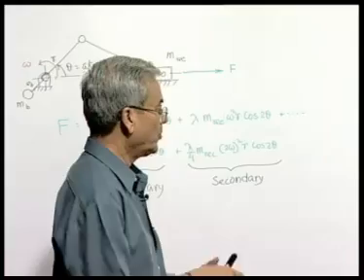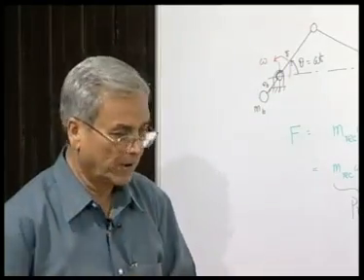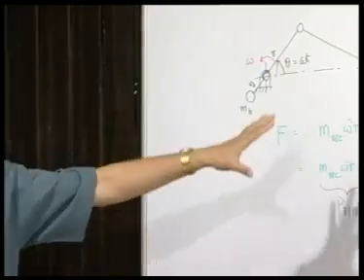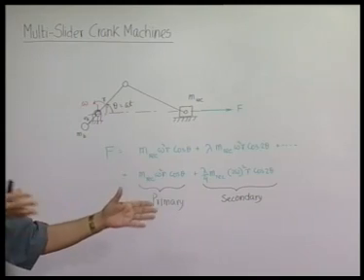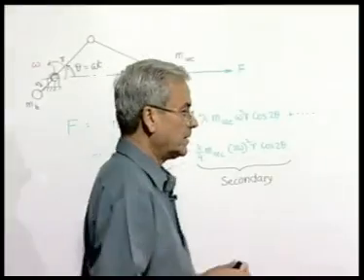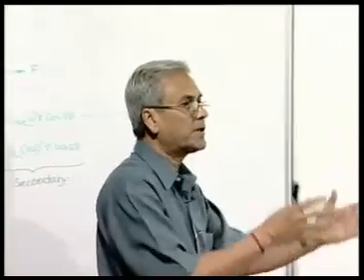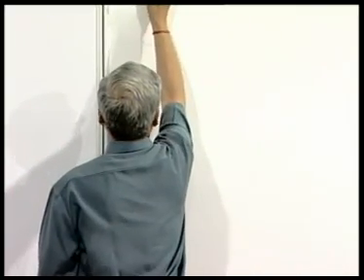And now, what we start discussing is precisely how to take care of the unbalanced forces in the case of multi-cylinder systems or multi-cylinder engines by suitable design. There are many ways in which these multiple slider crank systems or multiple cylinders in an engine can be placed. One most common example or situation is the inline engine.